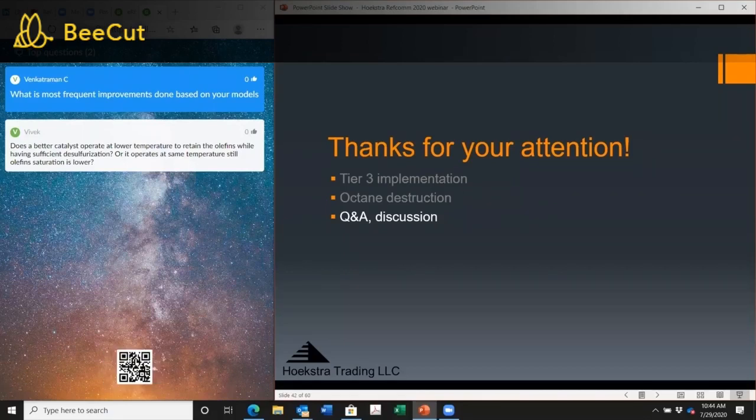But there are some reactions that happen with the aromatics, and we can see that because of the detail that we get in our analysis. So my contribution to that discussion would be to say that the aromatics can become an important participant in the reactions that go on in this unit, but it's not going to be the ones we think of that go on like in a cat feed hydrotreater, which is aromatic saturation. You can't get that reaction to occur at the kind of pressures that this unit operates.